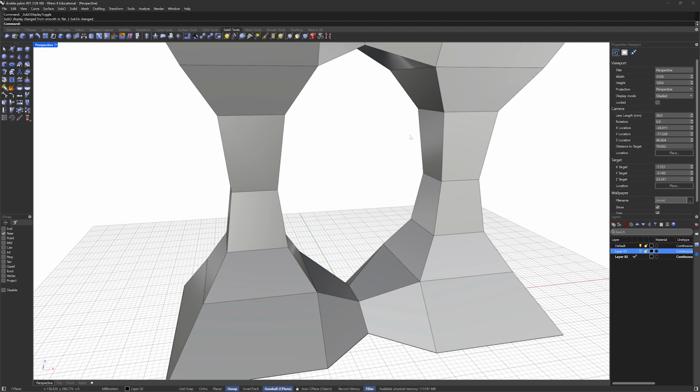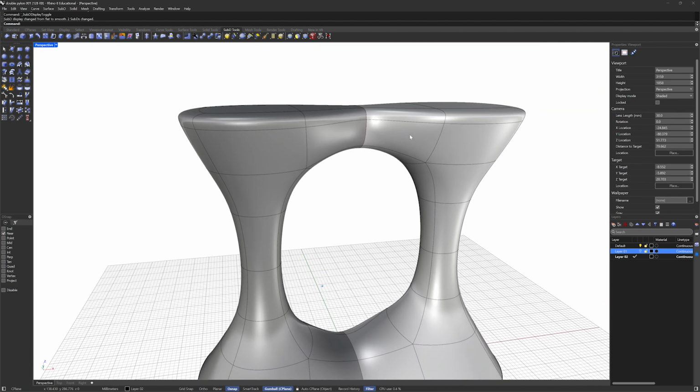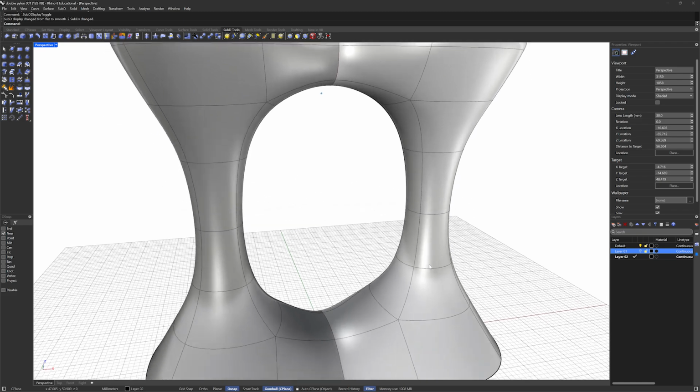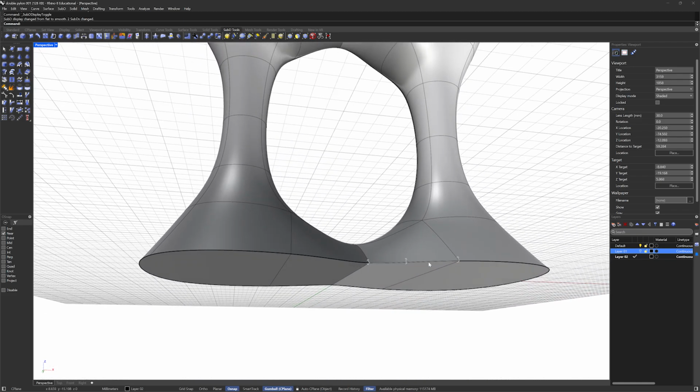Doing edits in box mode because it's faster to work with. And then at some point, when you're just about done, fake a fillet or introduce a sub-D fillet, which is called a bevel. So I'll do the last one with more segments just so you can see how it's a little bit sharper. So let's double click this one.